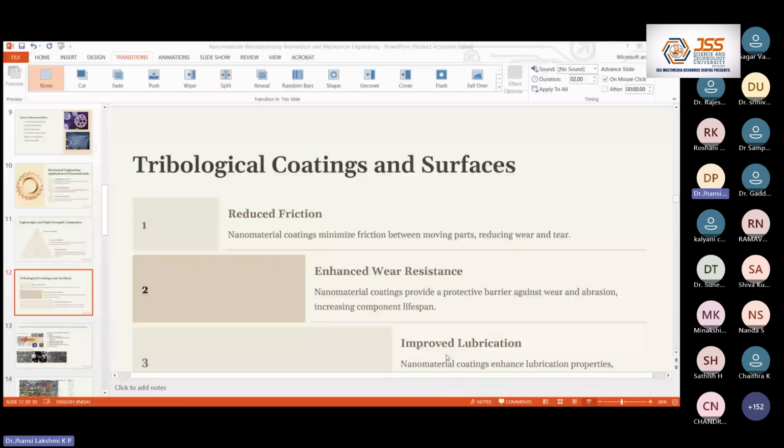Erosion wear tests were performed using the central composite design technique. We are varying B4C concentration, impingement angle and temperature in 4 levels. After designing the experiments and drawing the interaction plots, it is observed that 15% B4C plus 5% cenosphere and 20% B4C compositions showed similar erosive wear resistance. Maximum B4C composition exhibited maximum erosive wear resistance due to its hard carbides and oxides in the coatings.